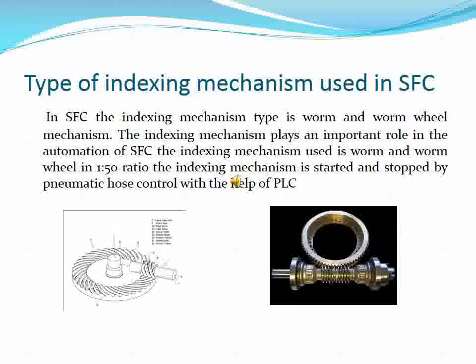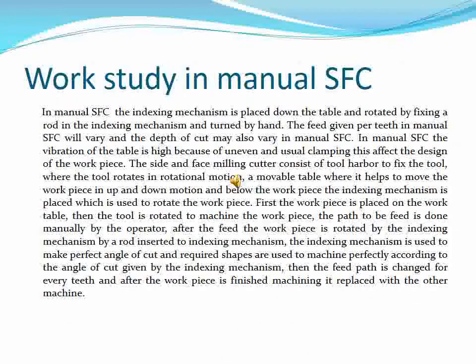The feed per tooth may also vary in manual feed because the feed given by the operator may vary from one tooth to another. The depth of cut will also vary since the operator cannot calculate the depth of cut for every single tooth of a workpiece. Proposed method of SFC.